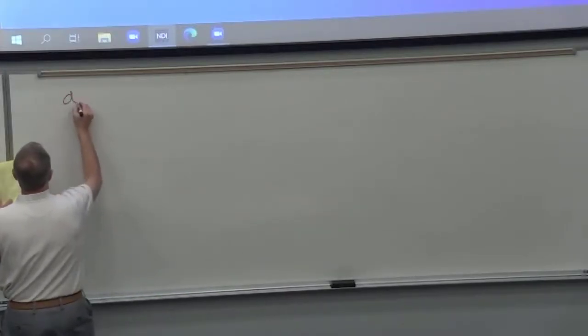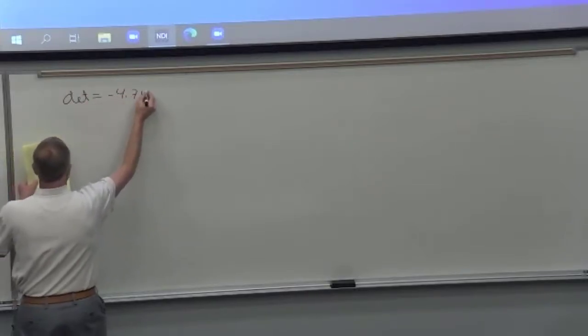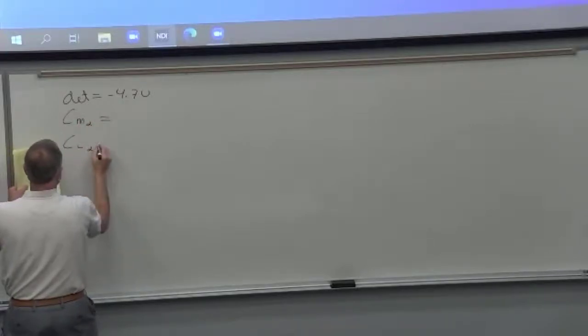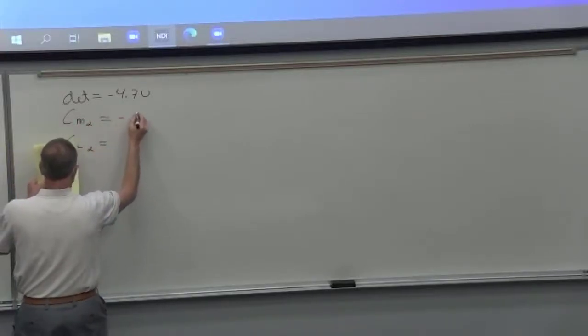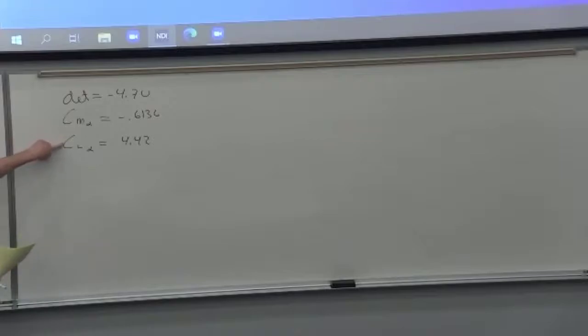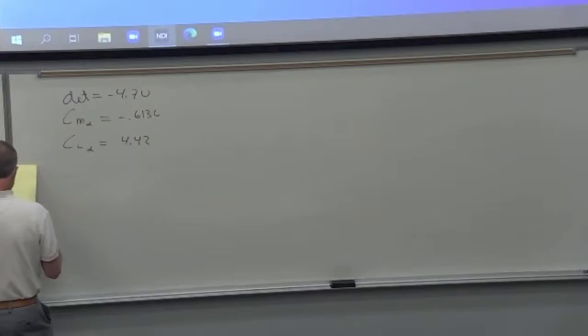So we need the determinant that we calculated from before for the 2x2 trim problem. And then we had CM alpha and CL alpha from back then, because we calculated them. Right, that's the curve slope of the entire airplane. This is the pitch stability of the airplane that we calculated in homework and for this example. And now we need the big formula.